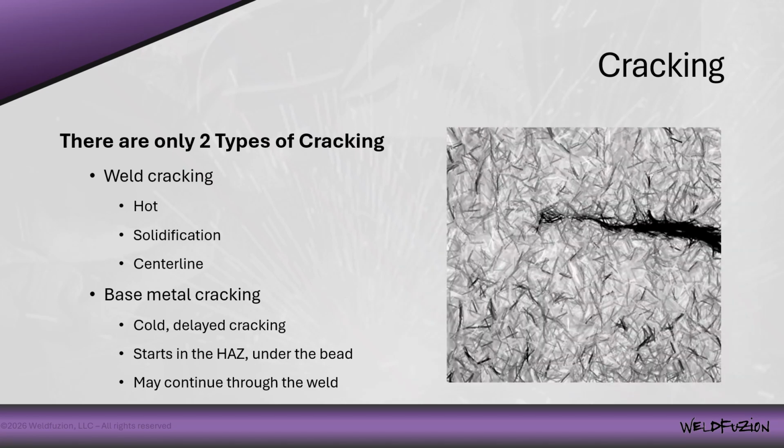Well, thankfully, solidification cracking isn't all that common in most metals, or base and filler metals have been formulated to resist it. So that's why we look up manufacturer recommendations as we match our filler metals, right? That's especially common in steel and stainless steel alloys. Those that are intended to be welded work together with the filler metals that are available. But filler metal selection has everything to do with your end results in terms of sensitive alloys, like aluminum.